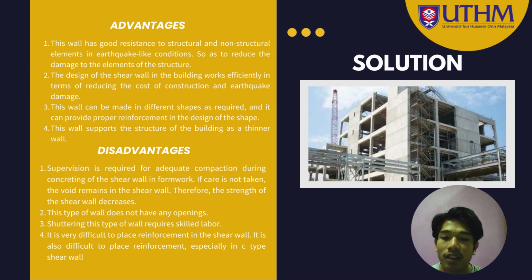This type of wall does not have any opening. Shuttering this type of wall requires skilled labor. And last, it is very difficult to place reinforcement in the shear wall. It is also difficult to place reinforcement, especially in C-type shear walls.